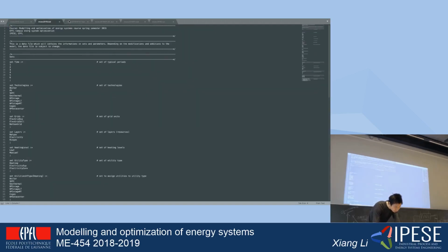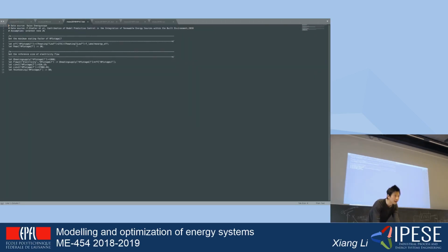And the first step you should do, in fact, is to integrate your results of part 3 and part 4 into our model. Basically, it's in the heat pumps. Here, in fact, you have two methods to integrate this kind of data into your MILP model. For example, in this file, low temperature heat, one-stage heat pumps, I define it in a way that the efficiency of the heat pump equals the exergy efficiency times the Carnot factor of your model. So you can change that.